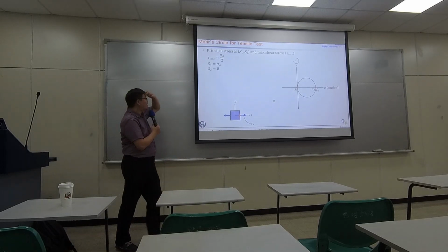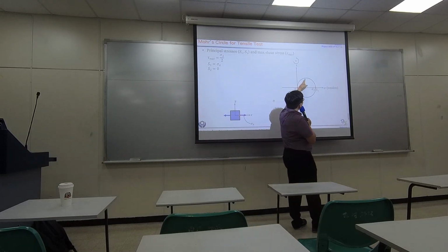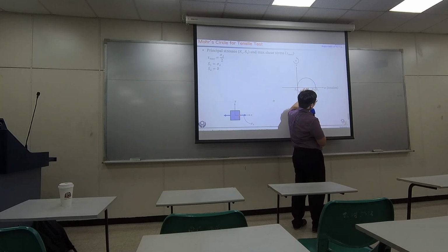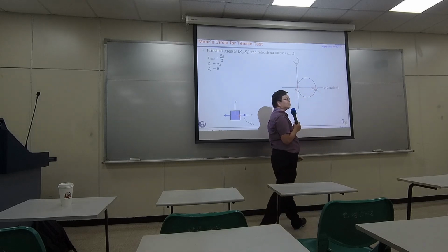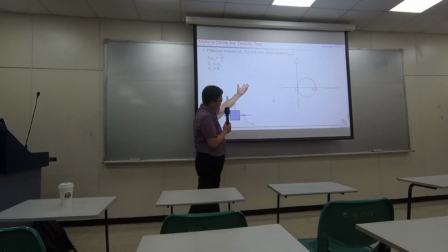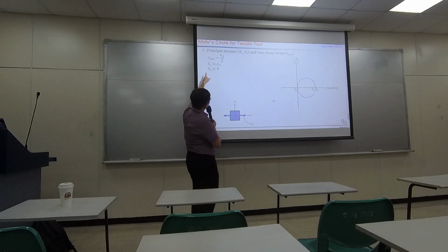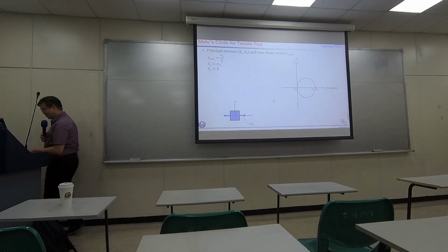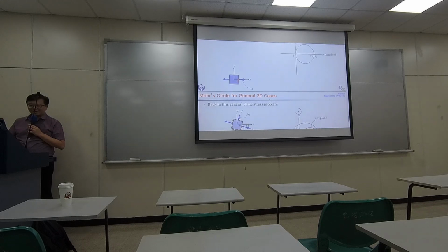There's one important parameter, which is the maximum shear. The tau max in tensile test is half of sigma A, right? Because of the radius. That number is important. Tau max equals sigma A over 2. That's important in future models. Keep that in mind.